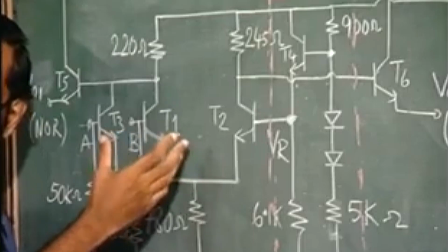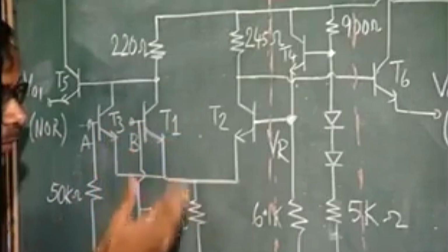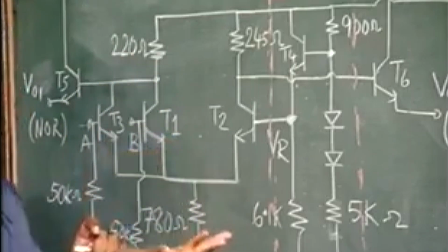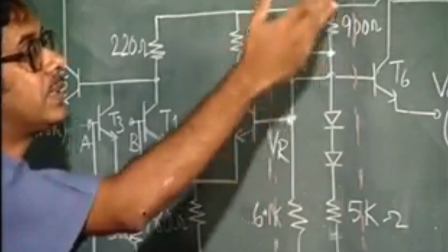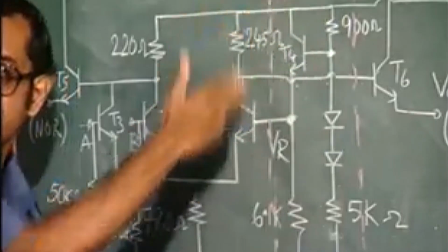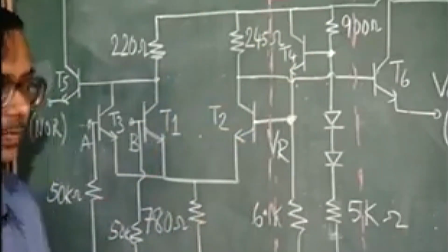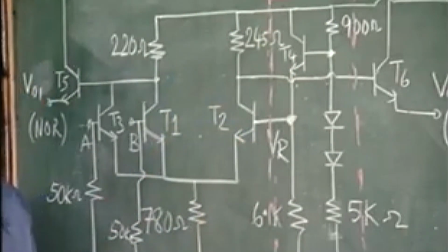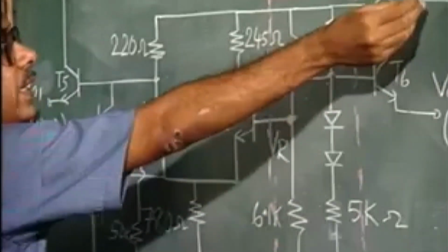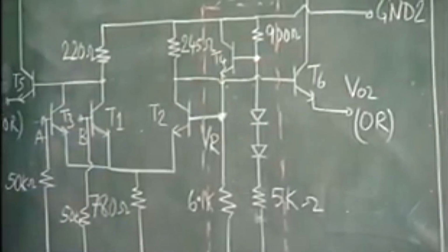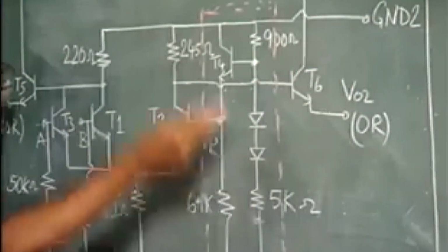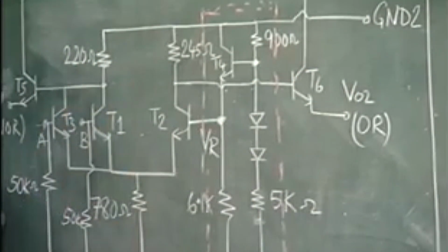It is just the total current which is being switched from one branch to the other. Also, for the reference voltage generation circuit, the current is almost fixed. So if you look at the circuit connected to this ground 2, the current flowing is almost fixed.